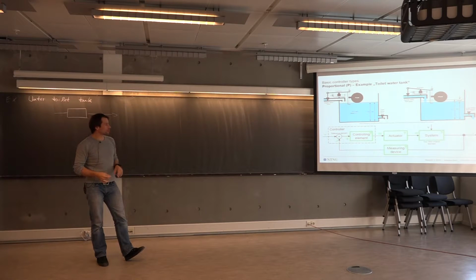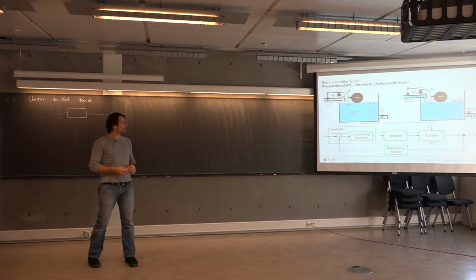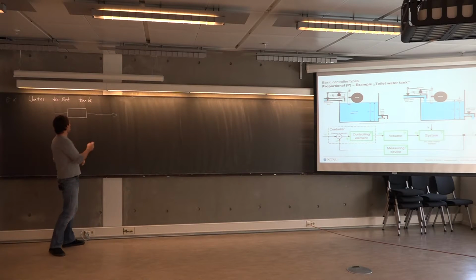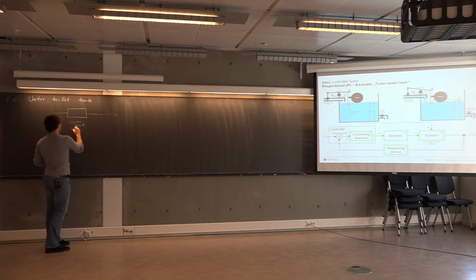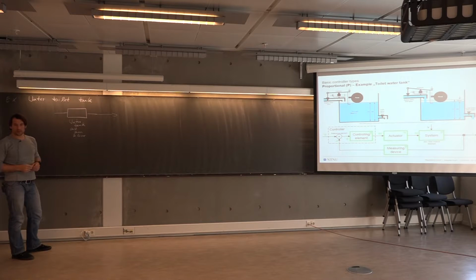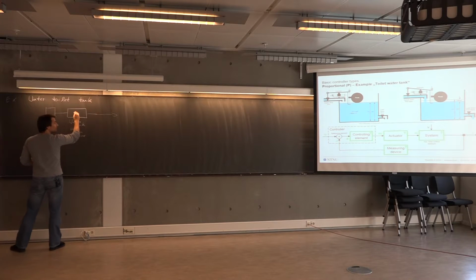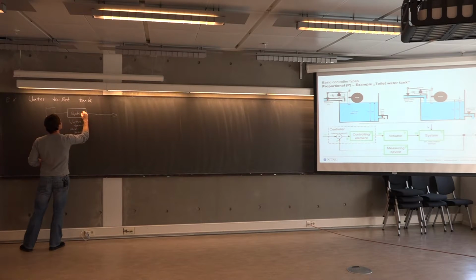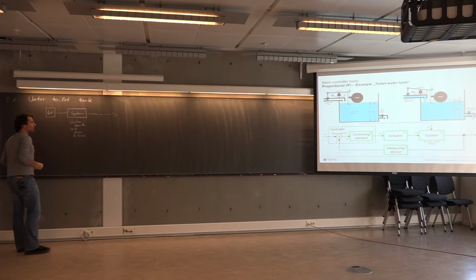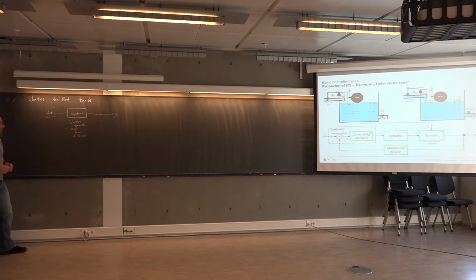But with regards to regulation and control, where we would like to identify elements such as the controlling element, the actuator and the measuring device, the system in this case is basically the water tank, excluding the valves and the lever, because at least the inflow valve, the actuator, is a separate item to be considered here.